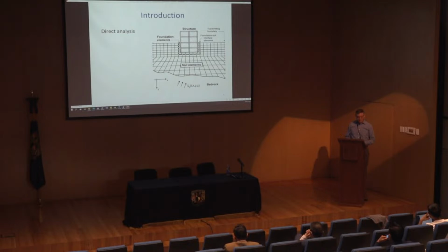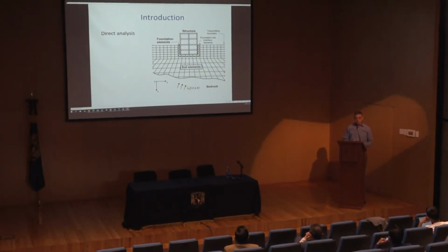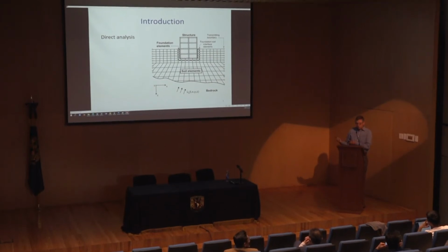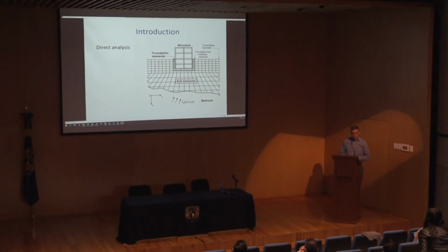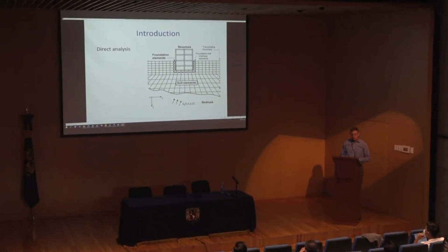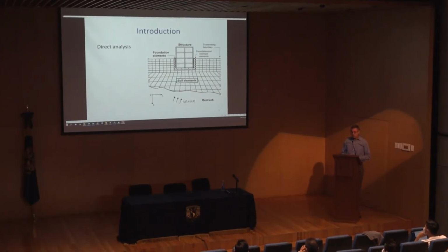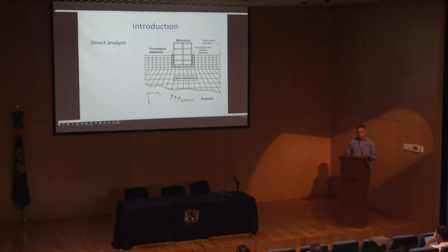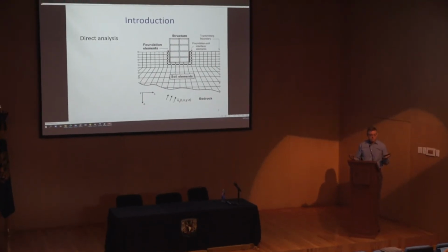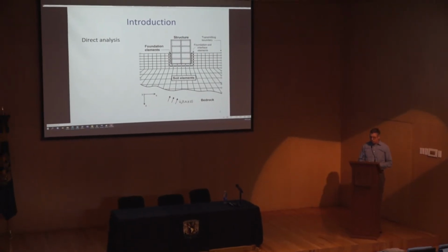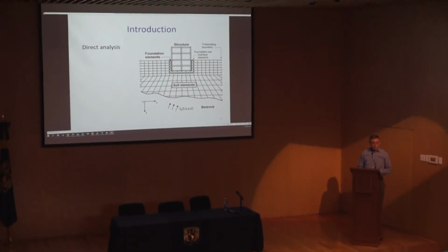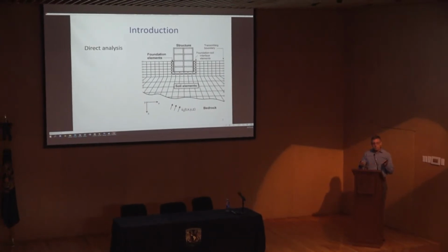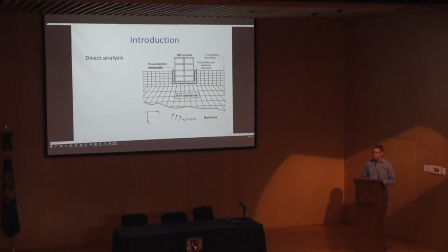So that's one way of doing it, and the guidelines reference those things. They don't get very specific about how exactly to do these soil structure interaction analyses, but they basically give permission to compute earth pressures that way. This isn't done very often, as you might imagine. It's very expensive, but it is done for some projects. One example would be a major transit station that is below ground in an urbanized area. You'll do these kinds of analyses for those structures. If it's a retaining wall for somebody's house, probably not going to do it. So at some point, you go from simplified to more complicated, and it's really driven by project budget.